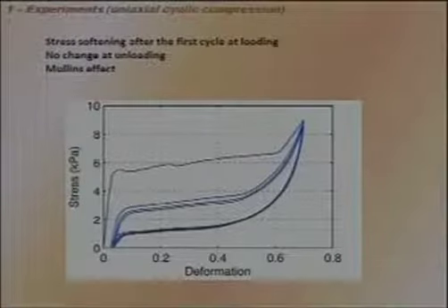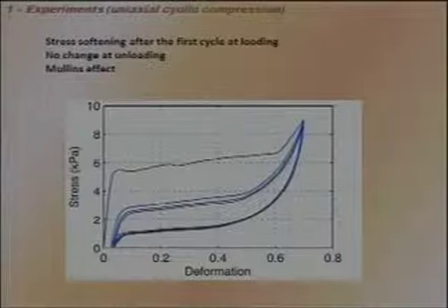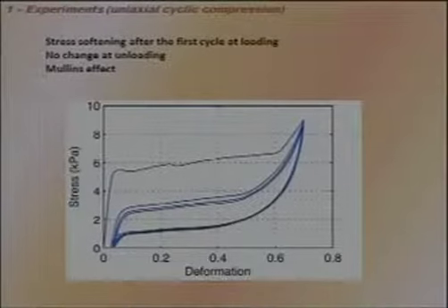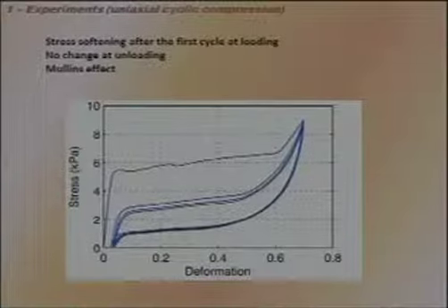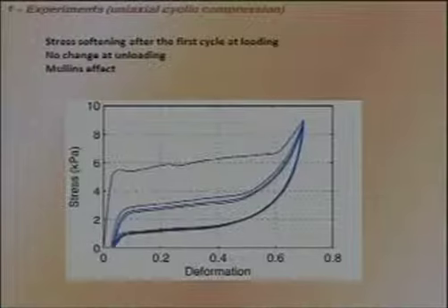But that's just the beginning, because if we do several cycles, it's a surprise that at loading there is a big difference between the first and the second cycle, and at unloading it's more or less always the same. So that's the second characteristic of the behavior of the foams.